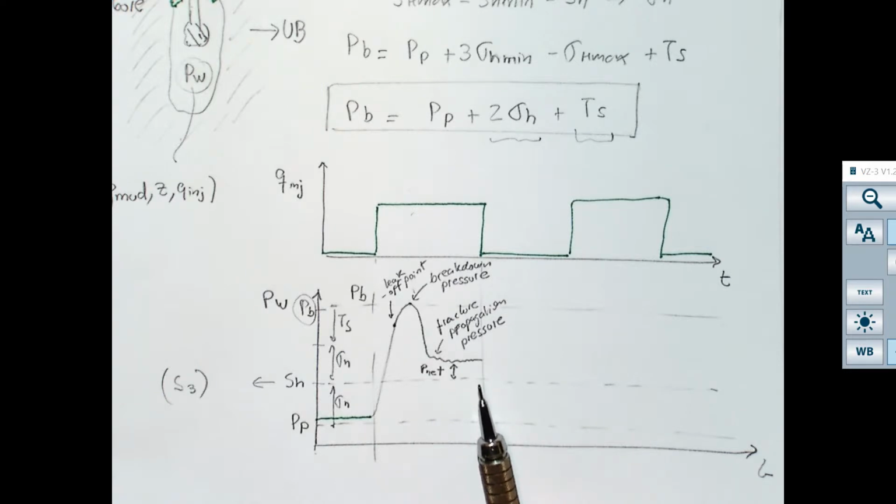The fractures are going to form at the velocity at which you are pumping a fluid. Because, for example, if you were to fracture a solid in vacuum, or if you were to fracture the screen of your cell phone, you can have those fractures open and they can propagate very quickly, okay? But in the subsurface, you cannot have a fracture open without something inside. And so, in the subsurface, in order to have fractures open, you need a fluid inside. And in order to have a fluid inside, you need to pump it in. So the fracture is just going to open at the velocity at which you're injecting your fluid.